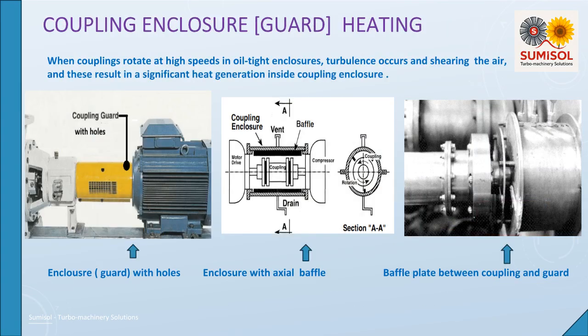The larger coupling flanges with higher number of bolt heads cause significant amounts of windage, resulting in frictional heating of the air in the coupling guard. Coupling guard volume, net cooling airflow, and clearance between the flanges and the guard internal wall become important factors. An improperly designed coupling guard results in unacceptably high coupling guard surface and internal coupling temperatures. Further, closed radial clearances effectively create separated hot volumes inside the guard.